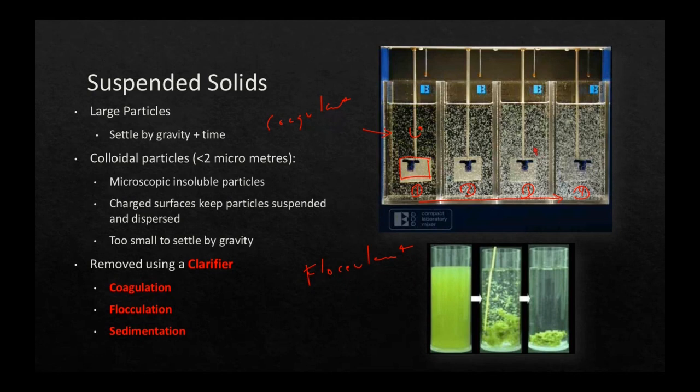So the coagulant is making these little things that we call flocks. All of the little visible colloidal particles now are called flocks. And a flocculant causes the flocks to come together into larger flocks. So flocculant makes large flocks.